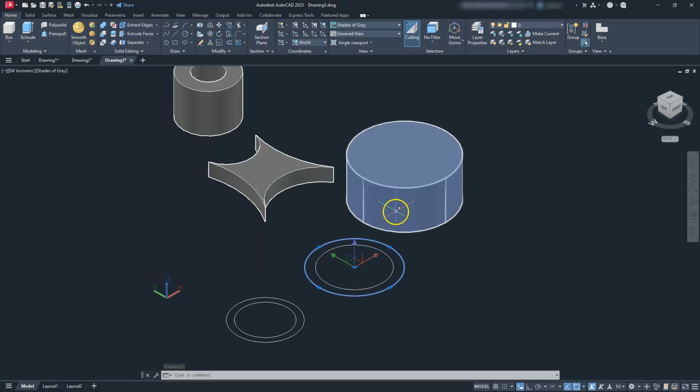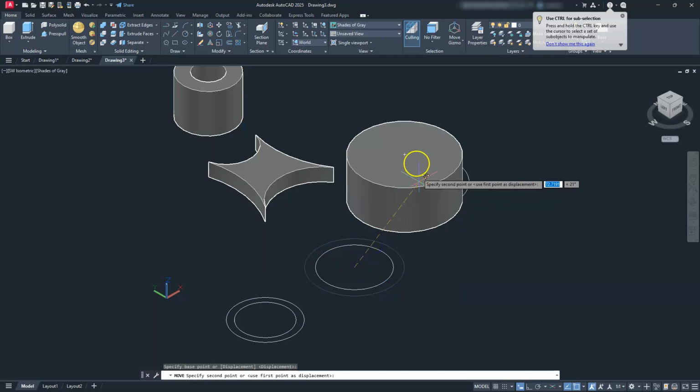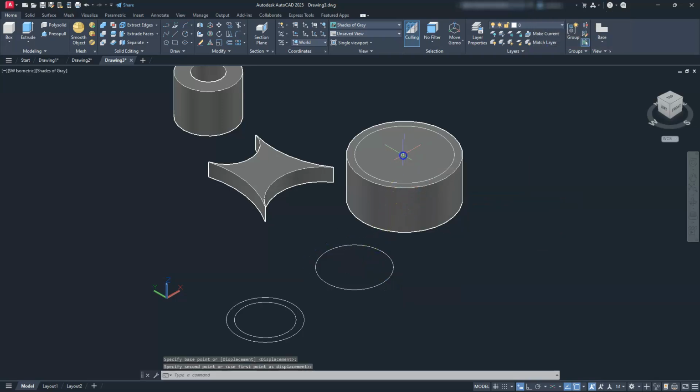And that's going to give me that offset that I'm going to use. So what I mean now is just go ahead and do it. I'm just going to go ahead and find the center here, click that center, and then go up to the center here and click on that center. If I use the extrude command from here, I can select just that circle, right?